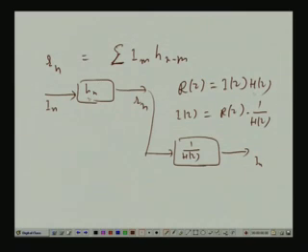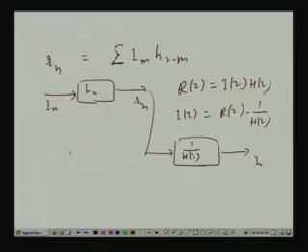So, in general some of the zeros can be within the unit circle and some of the zeros can be outside the unit circle. So, 1 by H z is a filter where the zeros of H z become poles. So, some poles are within the unit circle and some are outside the unit circle. So, it is a stable but non causal system, 1 by H z.